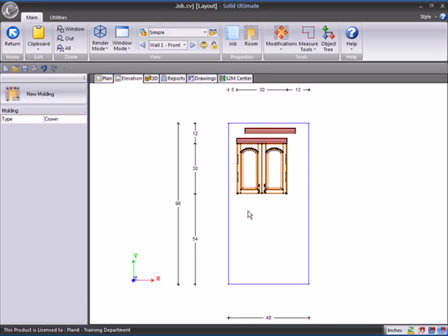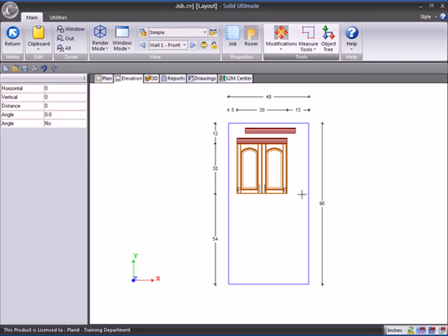Go back down to the lower right and snap to marks, where I can place my own snap marks. Let's go ahead and turn off the snap to cabinet points. Now I've got snap to marks, so I go up here and I turn on the snap to marks, and I'm just going to draw some points. Click the mouse anywhere on the screen and you'll notice my red snap marks show up.